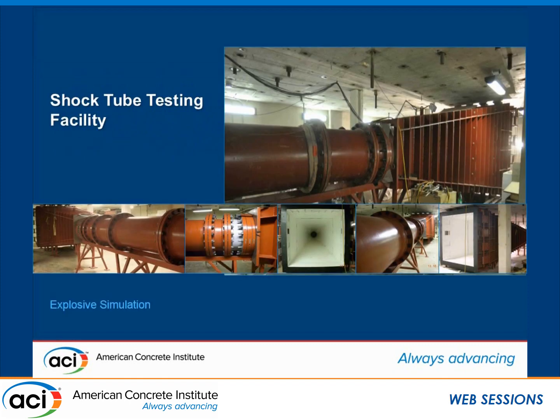So the shock tube facility, as was shown earlier, is comprised of a driver where we pressurize with high pressure air, and that's the tube at the back. That pressurized air is held back by aluminum diaphragms, and the diaphragms are burst, triggering a shock wave to propagate down the expansion section, which is aptly named. You could think of this as a confined wedge of the spherical expansion of a blast wave. Then the high pressure air interacts with the specimen mounted at the end. It simulates far range explosions, nothing too close to the structure. And as John was saying earlier, it certainly is nothing like the really close detonations that needed this catchment type of system.